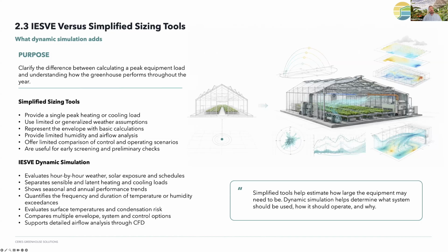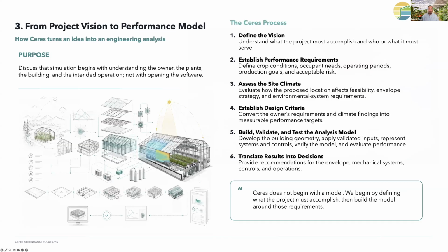It can separate the sensible and the latent loads. You can evaluate condensation risks, quantify the exceedance hours over set points, compare operating and control strategies, and support detailed airflow analysis through CFD. The distinction is between calculating a number and understanding a system that actually produced that number.